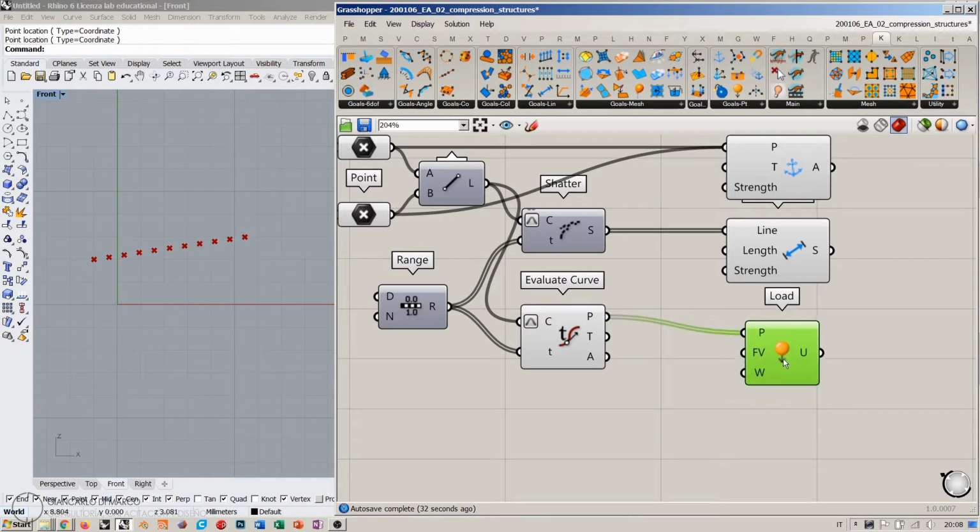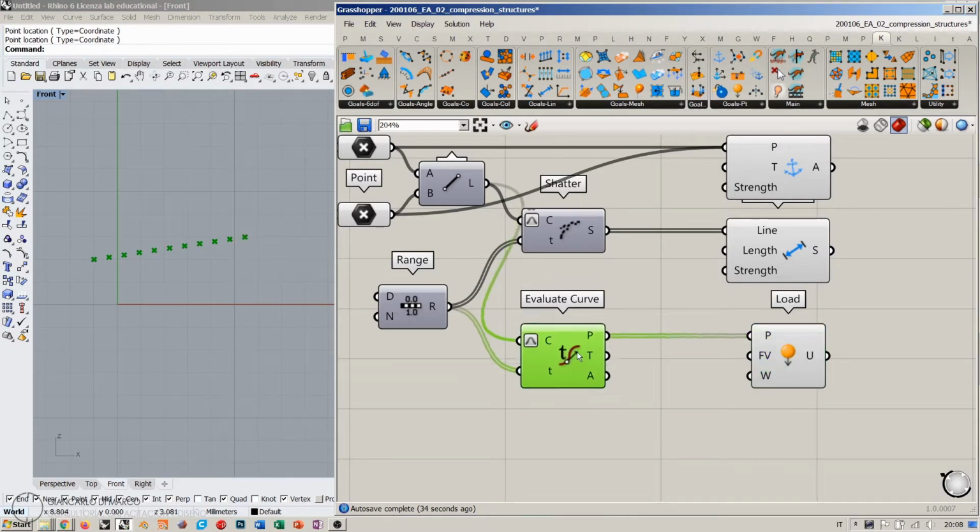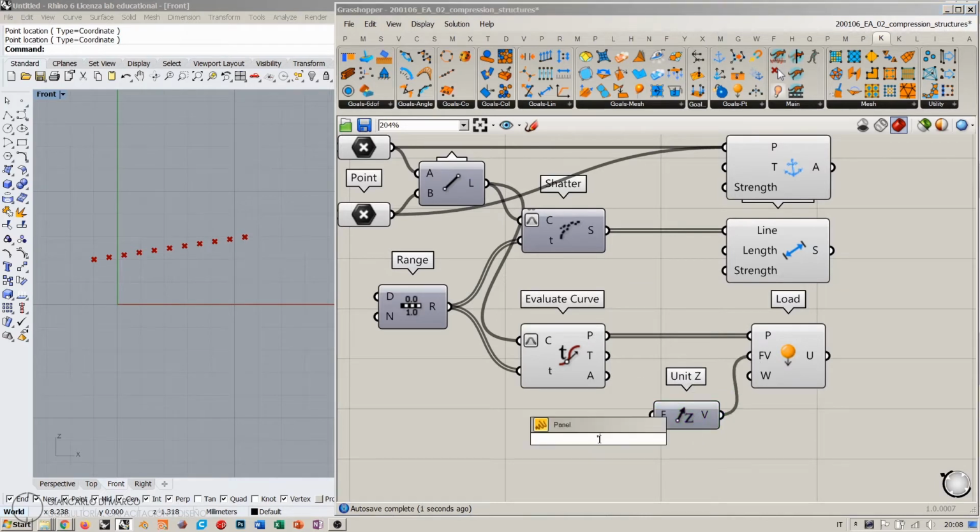But in this case, what I'm going to do is simulate this rope hanging from the endpoints. So I want to recover a real life situation where vertical gravity is oriented downwards. So I will take a unit Z vector, and I will say that its factor is -1.